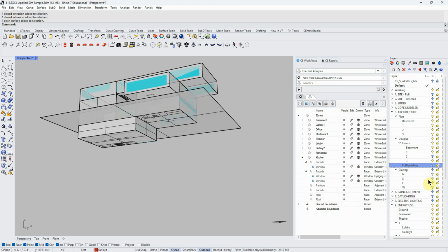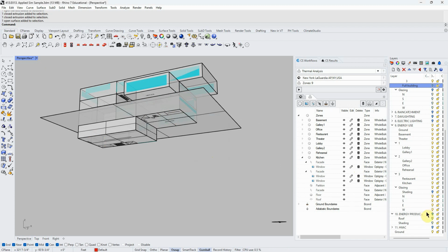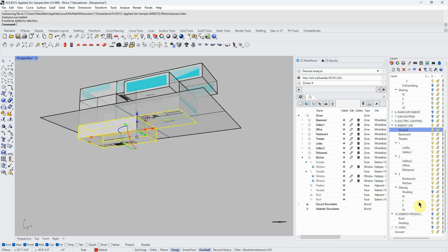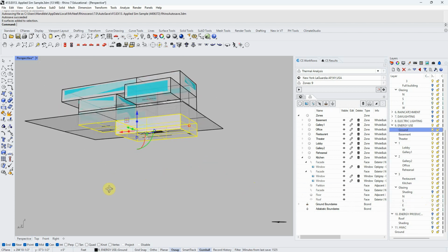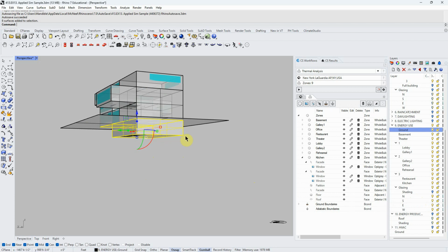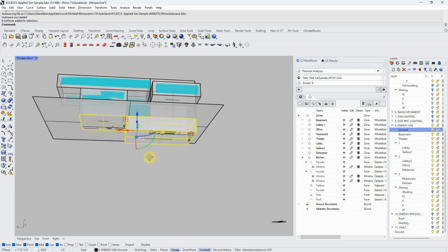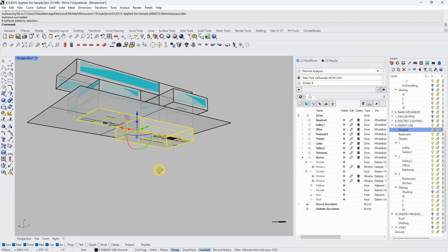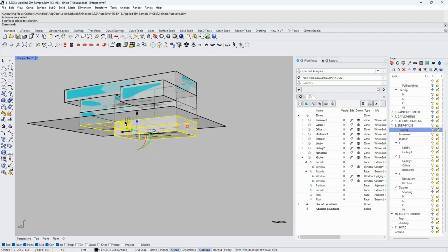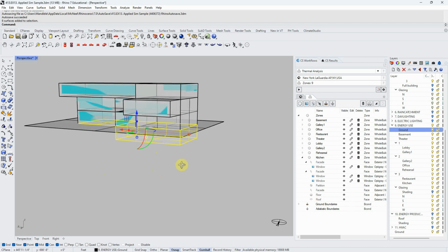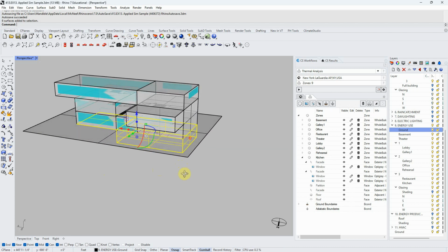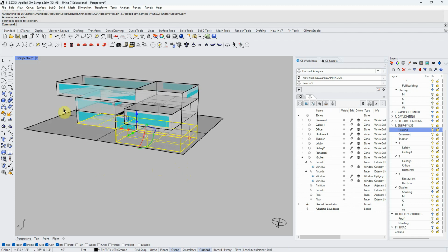Oops, I think I just have those as a unit here. Let me go see. All of these surfaces are the ground, because if you think about it, here's the basement, ground's all around it, underneath it, and then there's ground here underneath this floor. So that's important. Either keep it really simple and don't do that, or if I had this ground moving all the way underneath this building and I had the basement with grounds around it, it would not work, or I'd have some kind of error. So it might work, but it would be incorrect. So that's the ground.